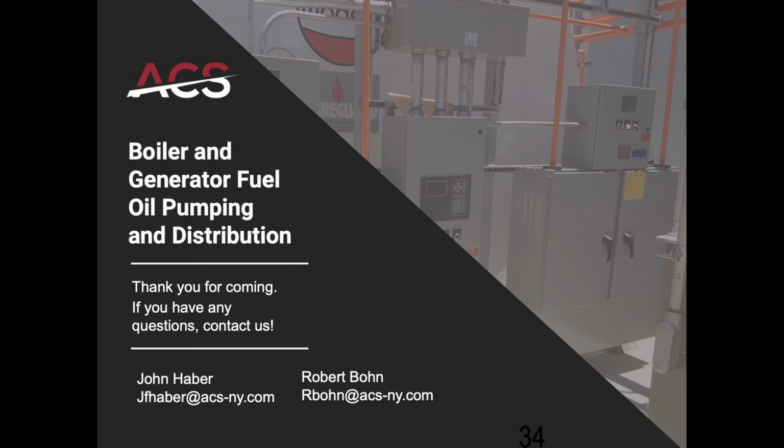Anything in a sub basement, third sub basement or below, you'll use your New York City alternate tank design. We have on occasion, in buildings with 5-6 floors below grade, used a 50 psi tank. So the head pressure on the tank from the height of that filled vent line will also determine your tank pressure. It's important to do that calculation on what back pressure you would put on your tank, and we have a calculator for that as well. We'd be happy to help out with that.